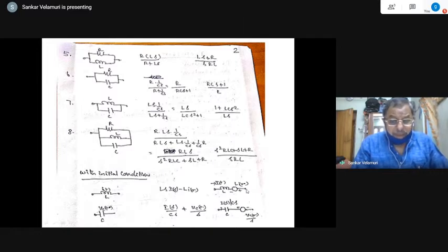And this is due to the current that is being obtained, not due to the rate of change of current. So L into I0 minus, whereas this is the integration of the corresponding current, which is the steady state current, and due to the steady state value, the corresponding charge. Q equal to the integral of that becomes charge. Charge divided by capacitance is the capacitor voltage that you know. That is why. Okay. So integration of the current is equal to charge. Charge divided by the corresponding capacitance will give the Vc0. Right. So that is how you have to treat this for the equivalent circuit.